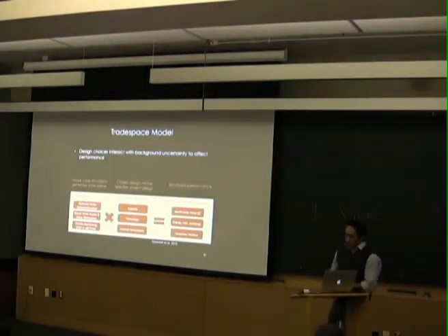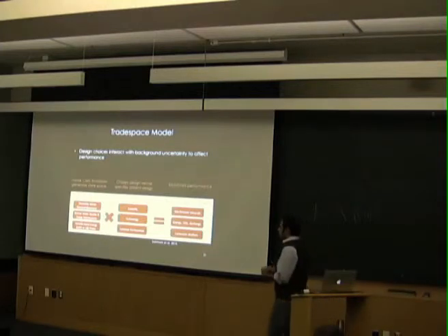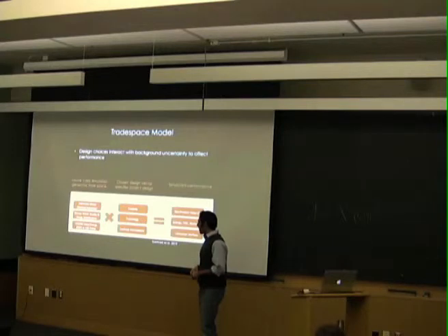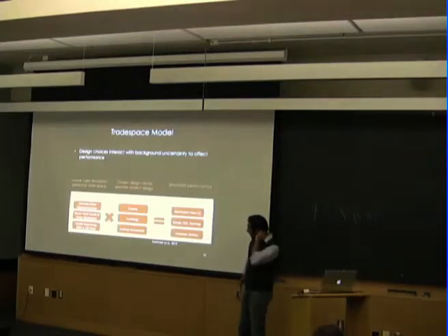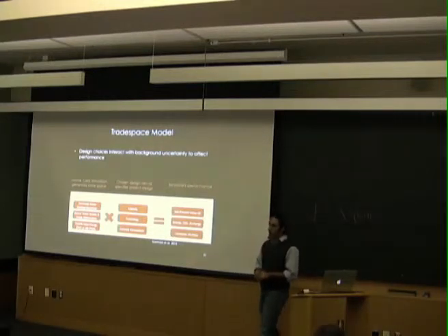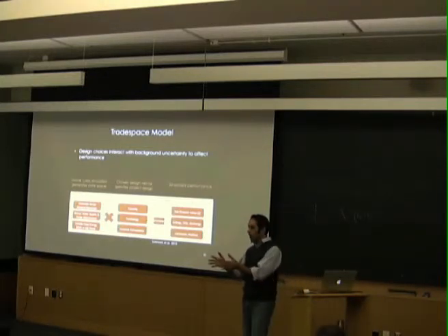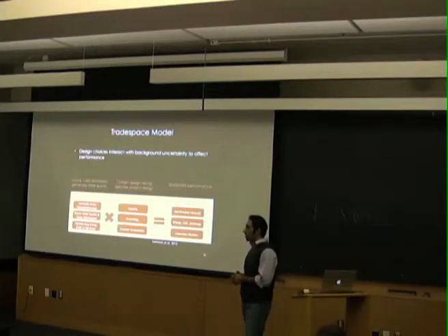So what do I do with this kind of information? So I built a simulation model, and basically I use some exogenous inputs like water demand, water quality variation, and temperature distributions, and then volatile energy inputs in what I call an uncertainty simulator, and feed that into a design choice interface. So this interface basically allows me to select MSF or MED or RO as a technology.